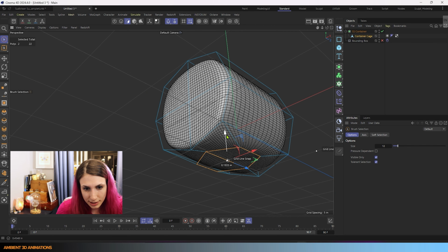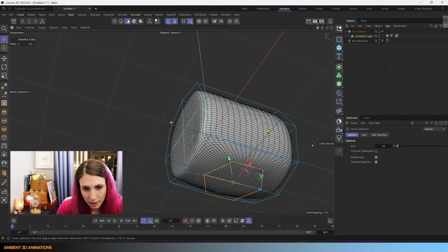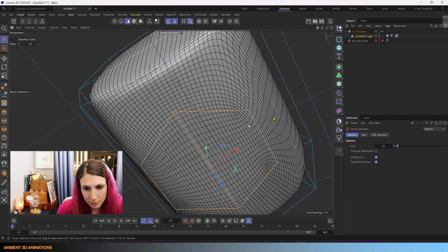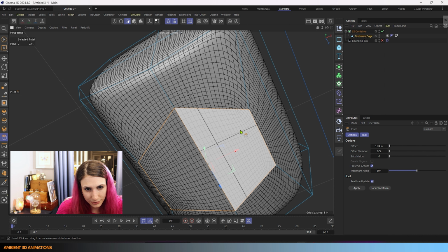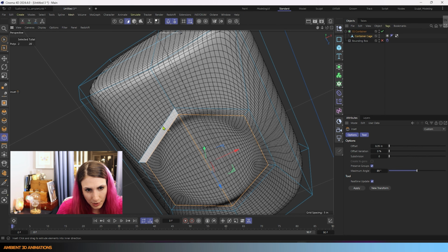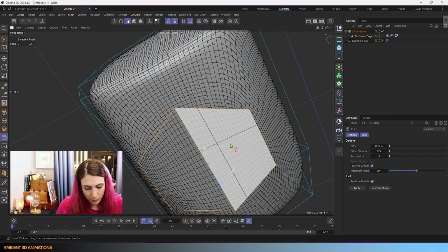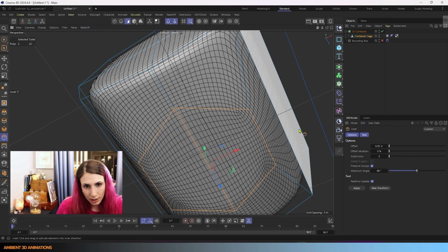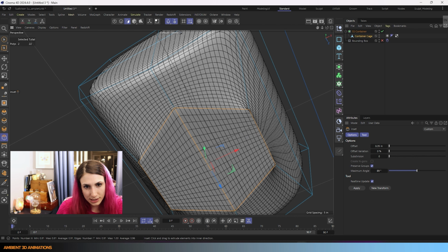Now that we have this here, we can lower this, and now we have a nice surface for this to actually sit on a table that's flat. And if we want to tighten this up a little bit, we'll use MW in order to subdivide that again a little bit this way, and we could do it that way. Or we could do something else, and we could hold the period button and click and drag off in space, and that'll start rounding it.